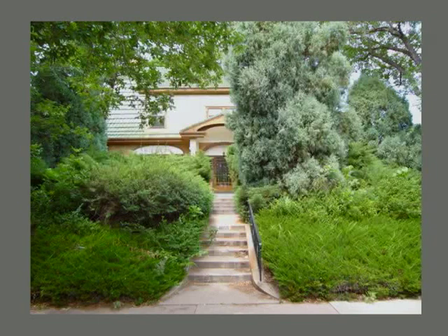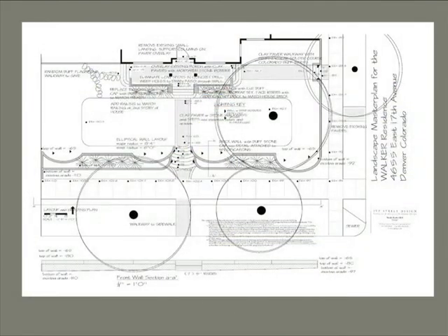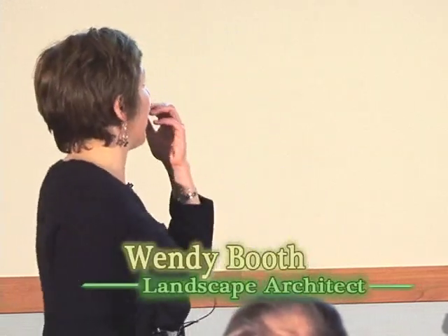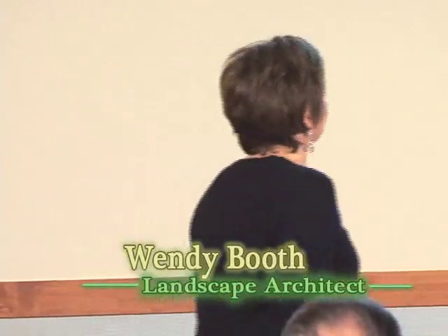So in our plan view here, the trees with the dark colored in circles, those are the existing trees, which when you're working around existing trees, you really need to keep the grade, the level, the same. You can't bring in dirt and cover up the feeder roots. You can bring in a little bit of dirt, but you can't cover them up a whole lot, or you deprive the tree of oxygen and cause it a slow death, which I think builders and contractors do a lot, and probably even landscape architects, because by the time the tree dies, everybody forgets why it died.